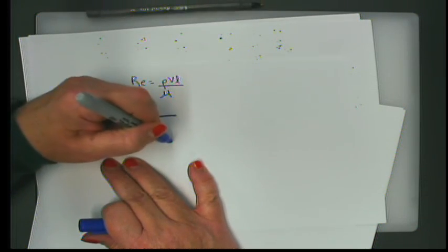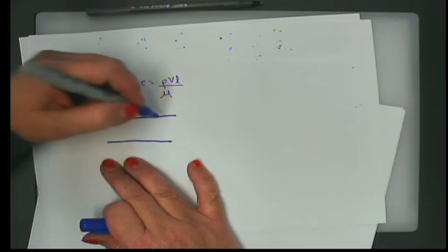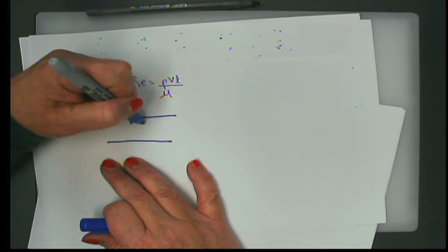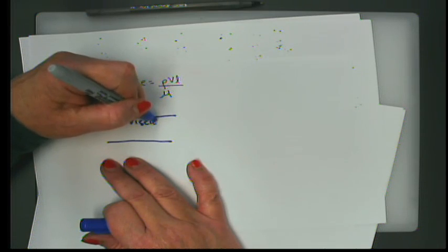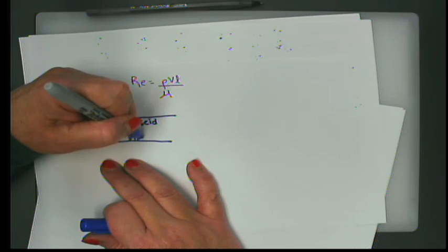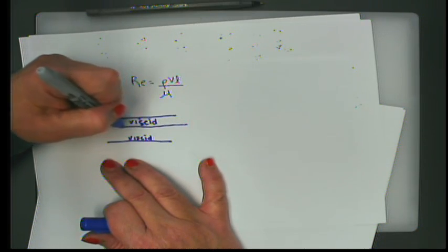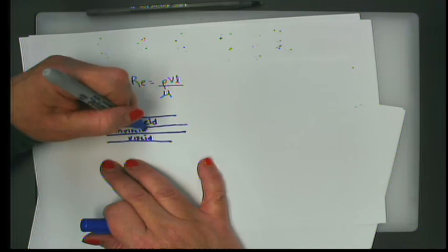And so when we start talking about boundary layer characteristics, what we're basically doing is we're dividing the flow into a viscid and an inviscid region. So if this is a pipe or a conduit, you'll have some region where the viscous effects are important, and then generally speaking, between the viscid layers, you will have an area where you can treat the flow as inviscid or ignore or minimize the effects of viscosity.